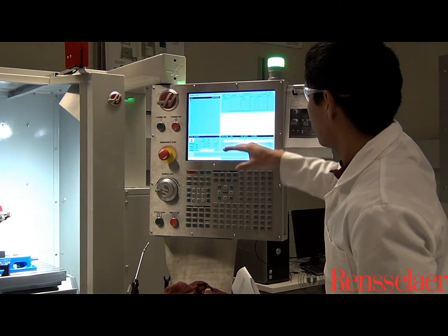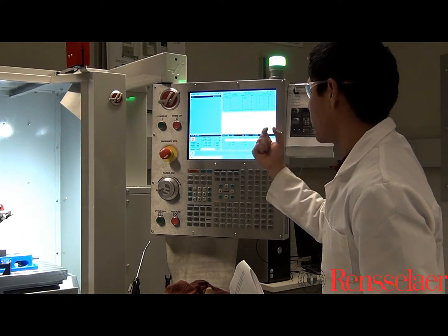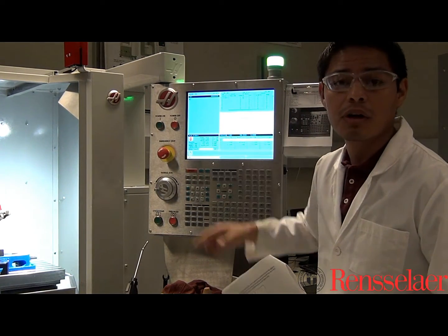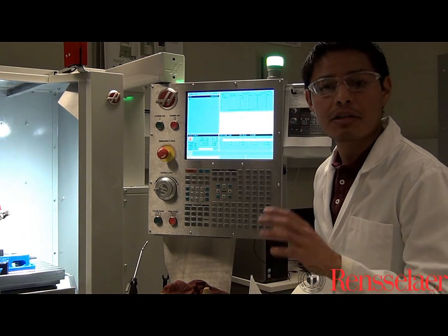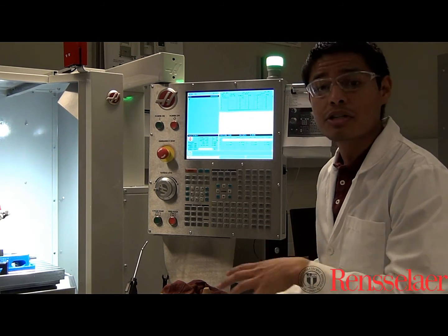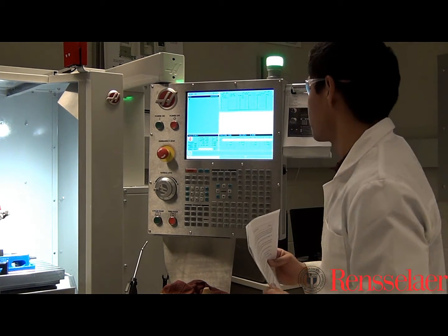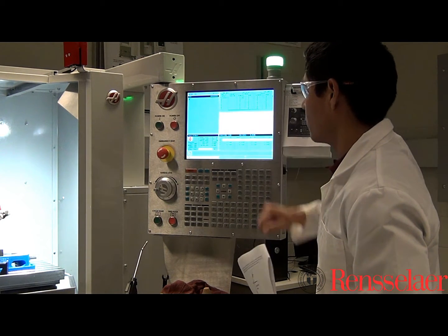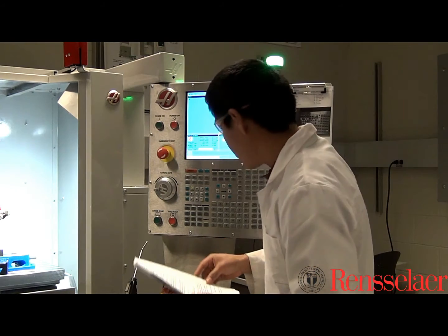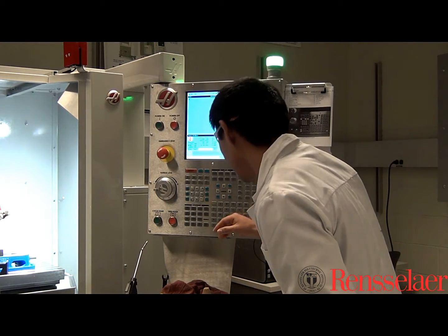Now, in terms of the G code, the most important line here is G54. G54 specifies to the machine your local axis origins in relation to your global axis origins. So like I said, we set our X axis and our Y axis. So what we're going to do now, we're going to press the part zero set